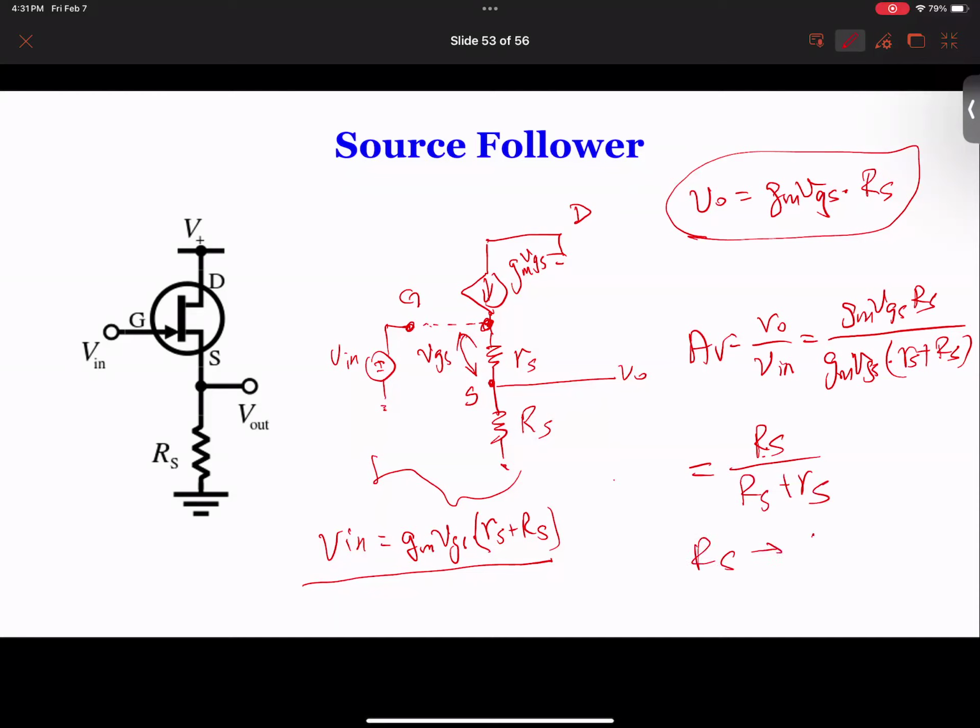But RS is typically in the 10 kilo ohm, and rs is typically in the 10 ohm. So just to give you, this is in the kilo ohm range, and this is in the ohm range. So you have kilo ohm divided by kilo ohm plus ohms. Basically, this can be almost neglected, and therefore this is equal to 1. So rs is much less than RS. So this is how we can find out the gain.